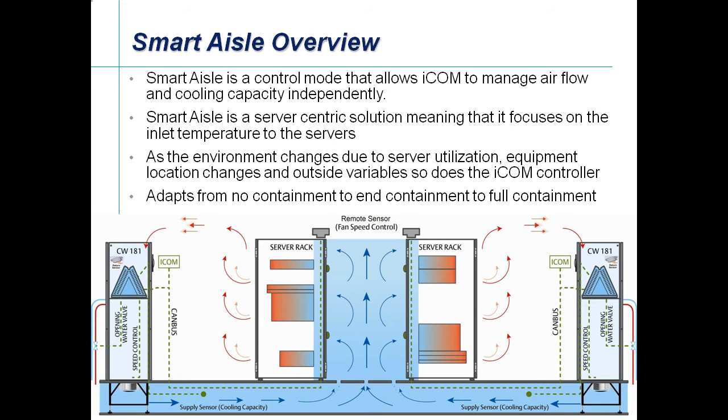So now that we are controlling at the source of our changing variable, we can change the application environment knowing that the cooling units will adjust to make sure your IT equipment airflow is met. If you decide to add containment, which provides better separation from the supply and return air streams, the fan speed of the cooling unit will automatically slow down because you have added a device that helps to direct the airflow where it needs to be. Another example is if you change the placement or quantity of your perf tiles, the cooling units will still vary the speed of the fans to make sure the airflow gets to the IT equipment.